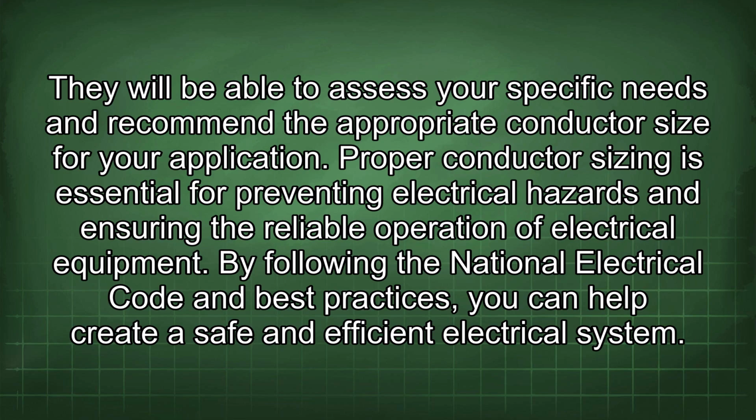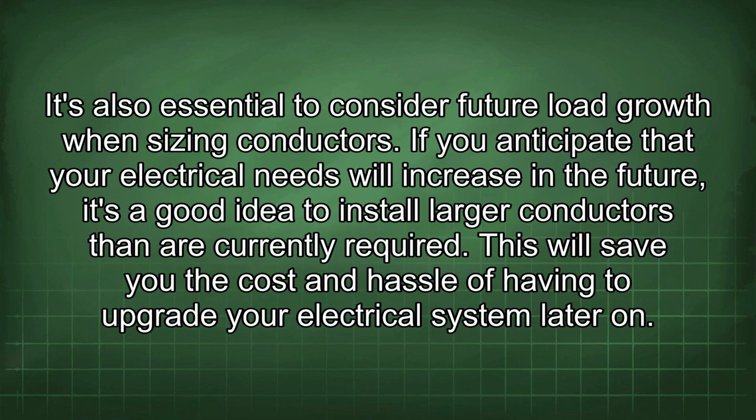Proper conductor sizing is essential for preventing electrical hazards and ensuring the reliable operation of electrical equipment. By following the National Electrical Code and best practices, you can help create a safe and efficient electrical system. It's also essential to consider future load growth when sizing conductors. If you anticipate that your electrical needs will increase in the future, it's a good idea to install larger conductors than are currently required. This will save you the cost and hassle of having to upgrade your electrical system later on.